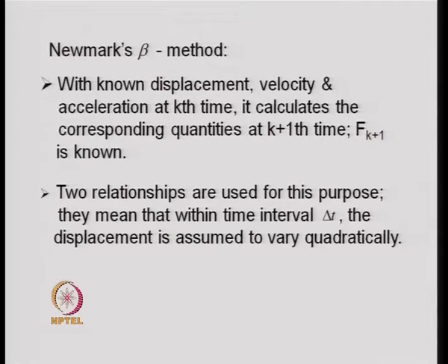So, that is the recursive form of the Duhamel integration, and it requires the solution of the problem for certain known cases. That is, the known cases are the damped free oscillation, the solution for a rectangular pulse, which also can be obtained using the Duhamel integral analytically, and the response for a triangular pulse, which also can be obtained using an analytical solution.